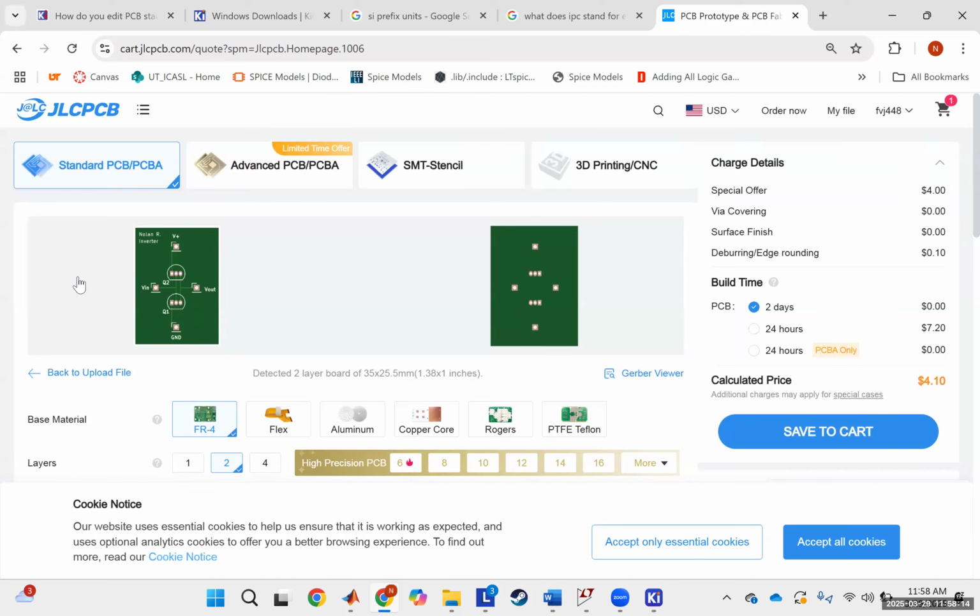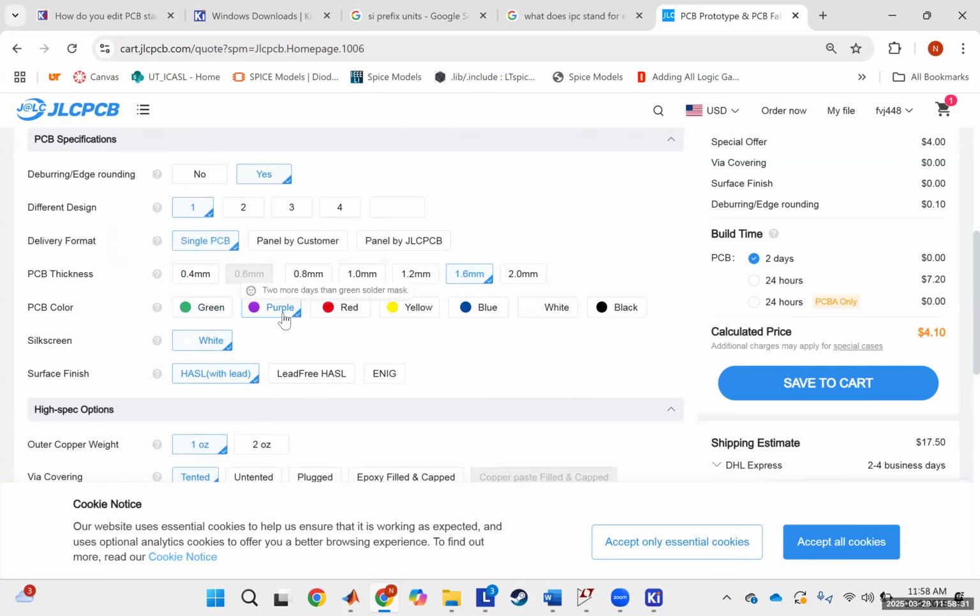So remember we said there's going to be different layers. There's going to be an FR4 layer, which is just a dielectric. There will be a prepreg layer. Then there will be your copper layers for your conductor. And then on top of all of that, they'll protect it with a silk screen layer, the green thing that you see from boards. But really, you can make it any color you want.